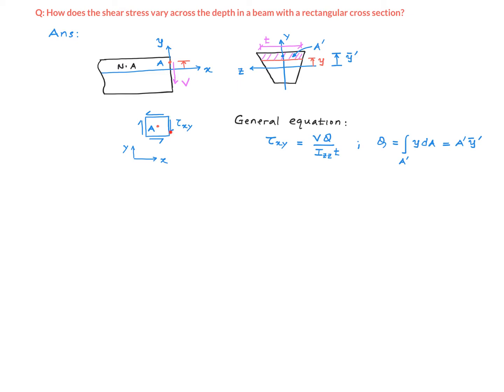Once we know the shear stress on any one of these planes on this two-dimensional differential element drawn around point A, then we know the shear stresses on all the other planes, because these are the complementary shear stresses, right?